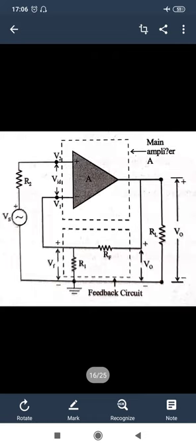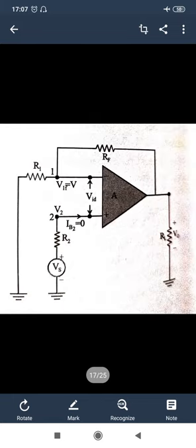So it is the simplified way where we use the op-amp and provide here VID as the difference at the non-inverting terminal. So here the feedback circuit is the parallel combination of R1 and RF, where V0 is taken across R1 and RF, and VF is taken only across R1, which is our feedback circuit. So it is also a simplified way.